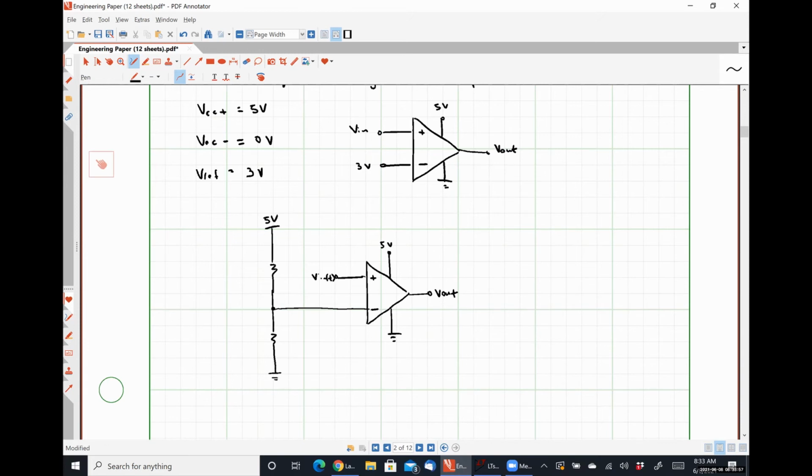So 2 to 3, okay? Where I'm going to say that the 3 one is here and the 2 one is here. So if I use voltage division, then I'm saying that 3 divided by 3 plus 2, or 60% of my 5 volt VCC signal, which is exactly 3 volts, is going to be my reference voltage.